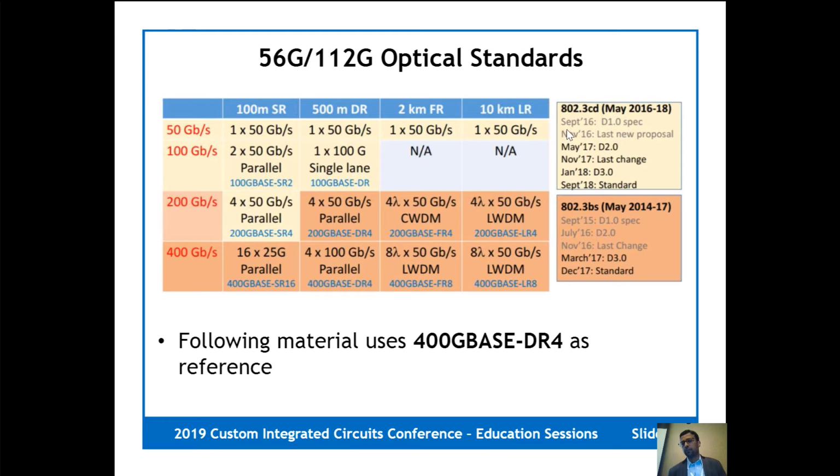And there's actually also standards being developed for 80 kilometers, so inter or intra-data, long intra-data center links using coherent optics that are not listed here. So for our purposes, we'll focus on everything 10 kilometers and below, because to a large extent, we can neglect the effects of fiber dispersion in that regime.